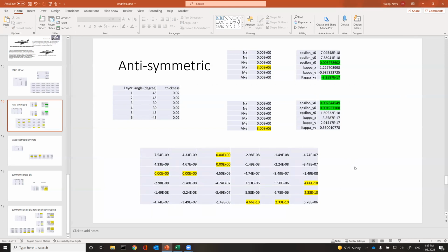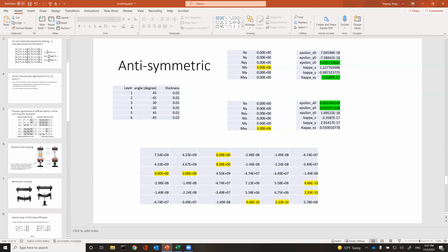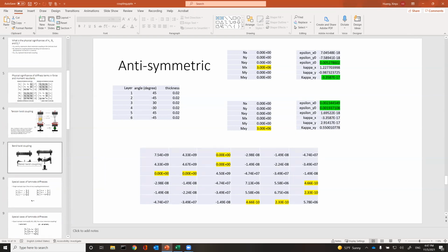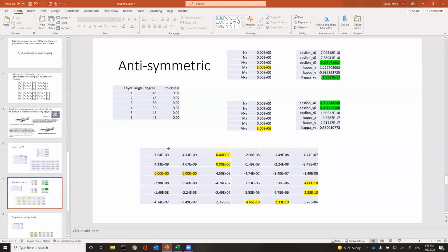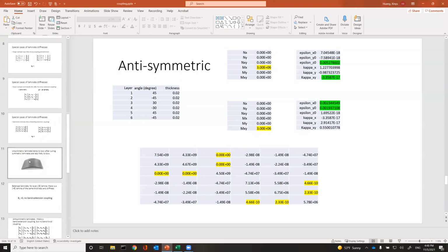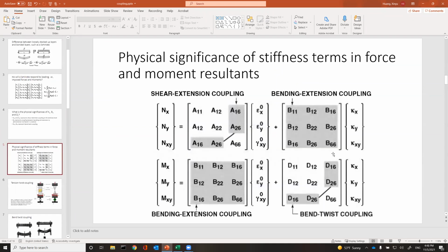All right. These are basically the important types. What we played with is a symmetric laminate, an anti-symmetric laminate, and also isotropic laminates. You can see the coupling phenomena in composites is pretty rich, and you can tailor them by playing with the layups. I believe we went through all the general types. So the B matrix is really controlled by whether you have symmetric, unsymmetric, or balanced type. If you're symmetric or balanced type, then it's 0.